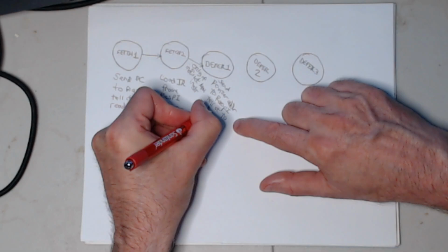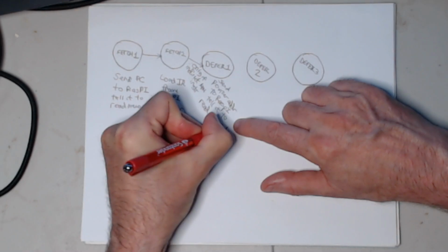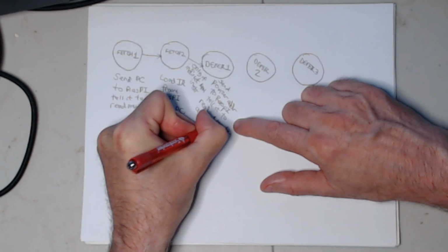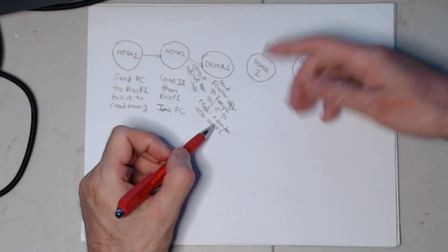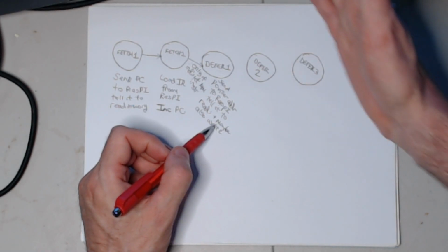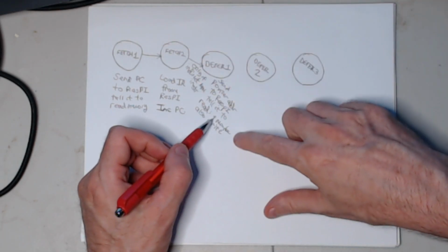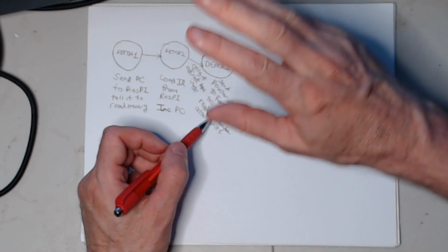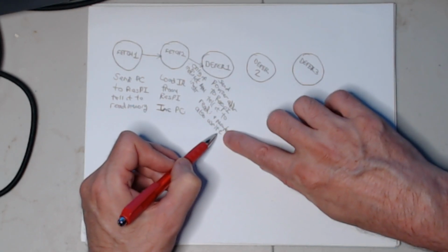So maybe also write. Okay, so if the pointer address is anywhere from 0010 to 0017, we'll also set this bit to tell the Raspberry Pi, okay, it's a read and then it's a write as well.